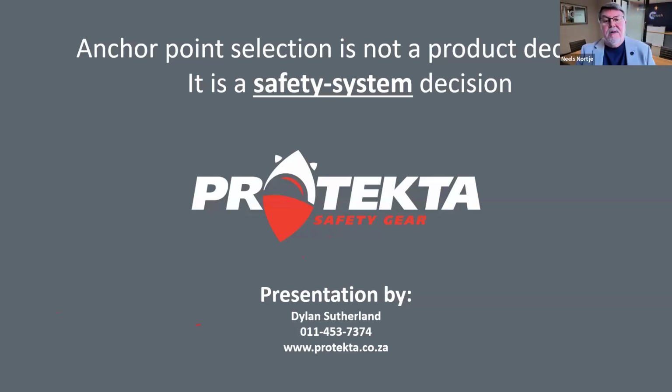All right. Great. Okay, the next question regarding the proof load pull testing for anchorage points, what type of documentation evidence would be considered acceptable to demonstrate compliance? This is so tricky and a really awesome question. The problem is the reality of us being able to do a proof load is you would probably need to use the device connected to the anchor, pull it. Then you would need to film that for 3 minutes at least, depending on what the OEM calls for.